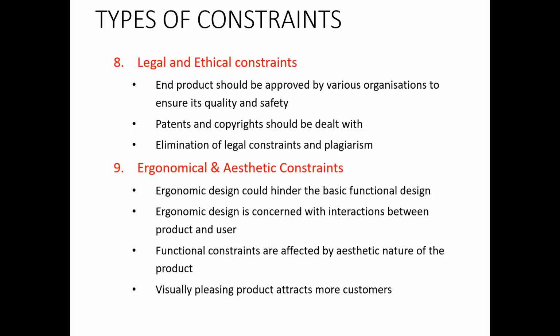How the product is going to be used by the user, whether the product is going to be user friendly, whether the customer is very satisfied or comfortable in using the product or not. The functional constraints are affected by the aesthetic nature of the product. So when we are trying to incorporate or add more aesthetics or comfortability to the product, then some functional aspects are affected.